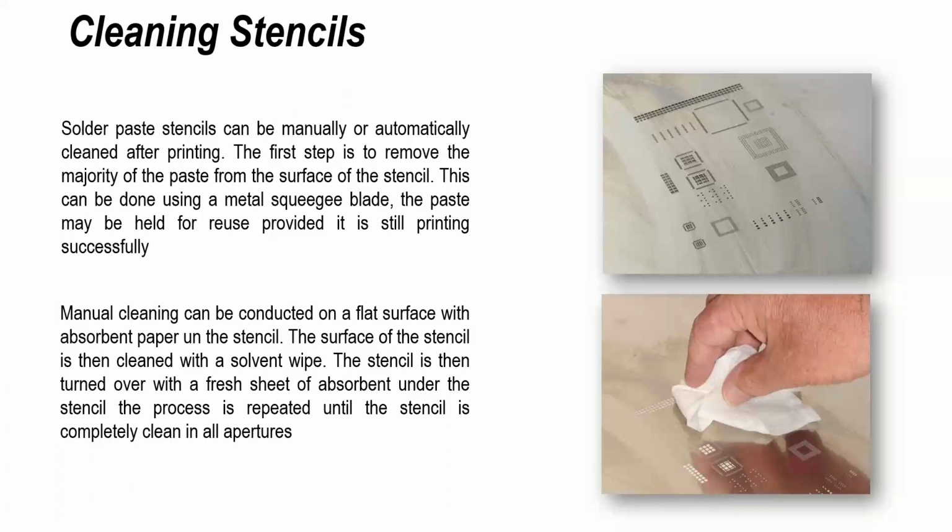So manual cleaning works and can work. It's not the ideal, but it can work. And I've got a procedure which I use for cleaning stencils manually and semi-automatically, and also inspecting the stencils afterwards. But the first key thing is making sure that you clean the stencil.